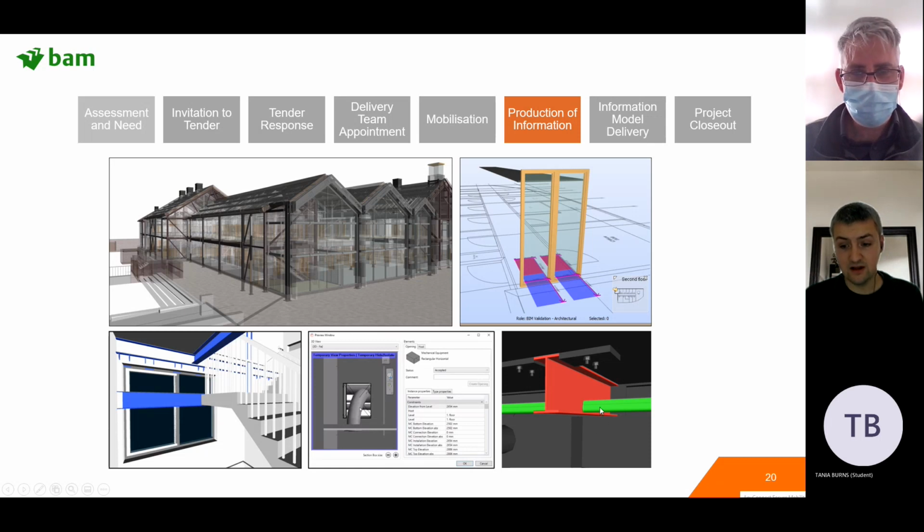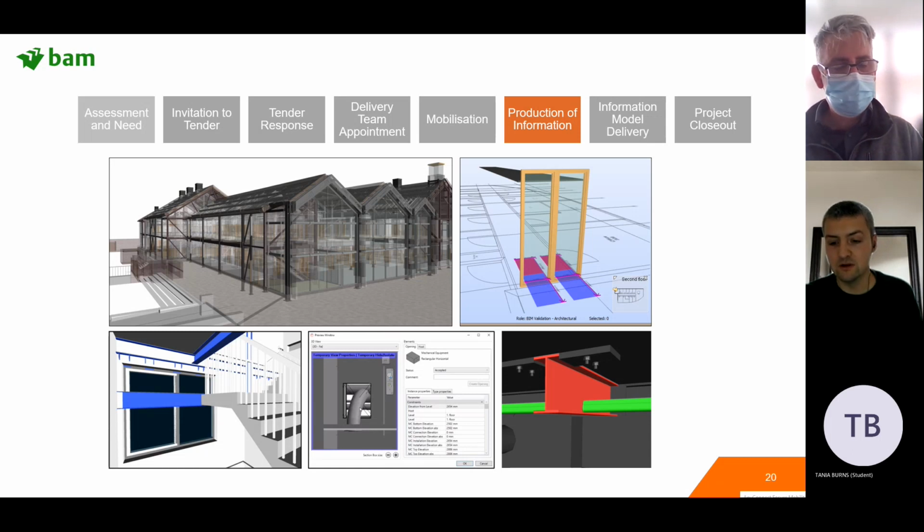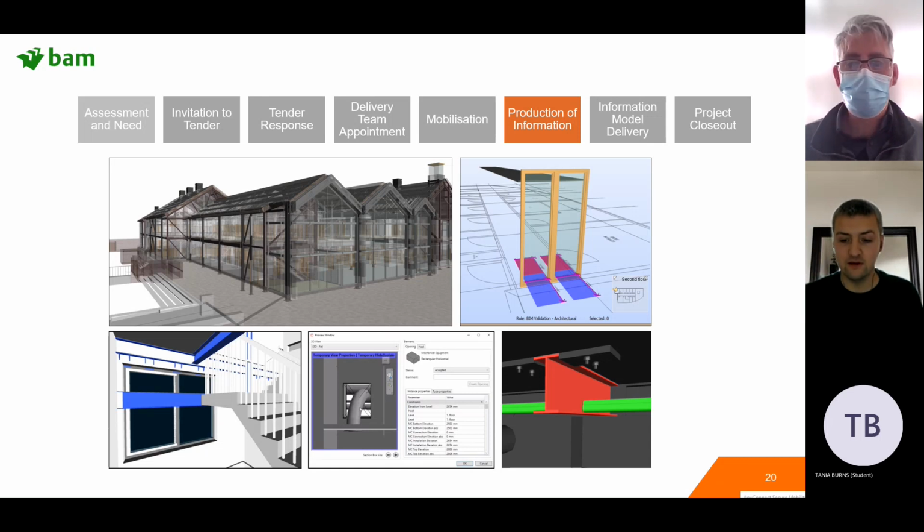This is just an example of a clash result. Pipes going right through a steel beam. So those pipes have to come down. And if that's happening on site, you've already started to set things out at that level, and they're realising they're going to have to divert the pipe down and try to go under it. They're hoping they're not going to catch the ceiling as they do that. These are things you want to design out in 3D before you get to site. Otherwise, there are delays and costs to addressing these problems on site.